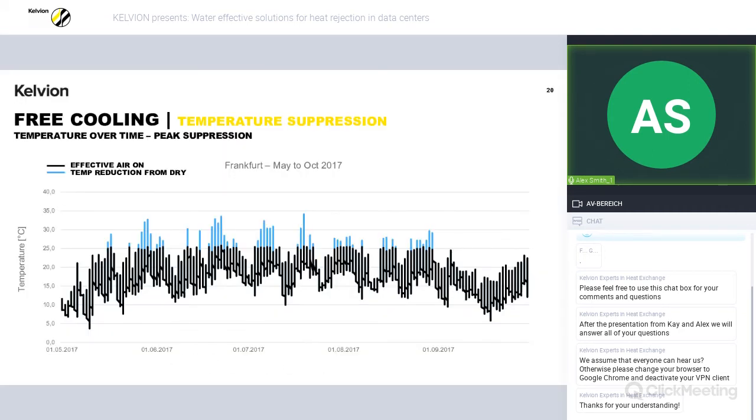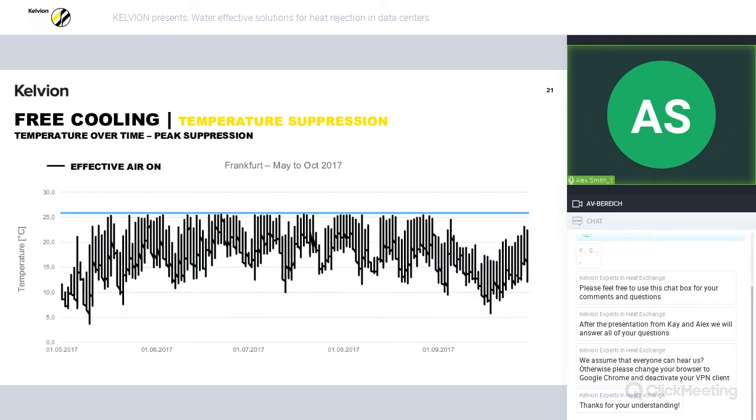Like so. In the situation depicted in this graph, water is only applied when the ambient temperature exceeds a given set point, determined by the expected extreme conditions. The resulting effective air temperatures are shown again in black. In this case, when doing so, we can limit the air temperature to around 25-26 degrees, as shown by this blue line here. This allows for more predictability in performance by providing a safety for ambient spikes and minimizing water consumption, whilst also allowing for an increase in free cooling hours, potentially even eliminating the need for mechanical cooling entirely if the thermal profile allows.